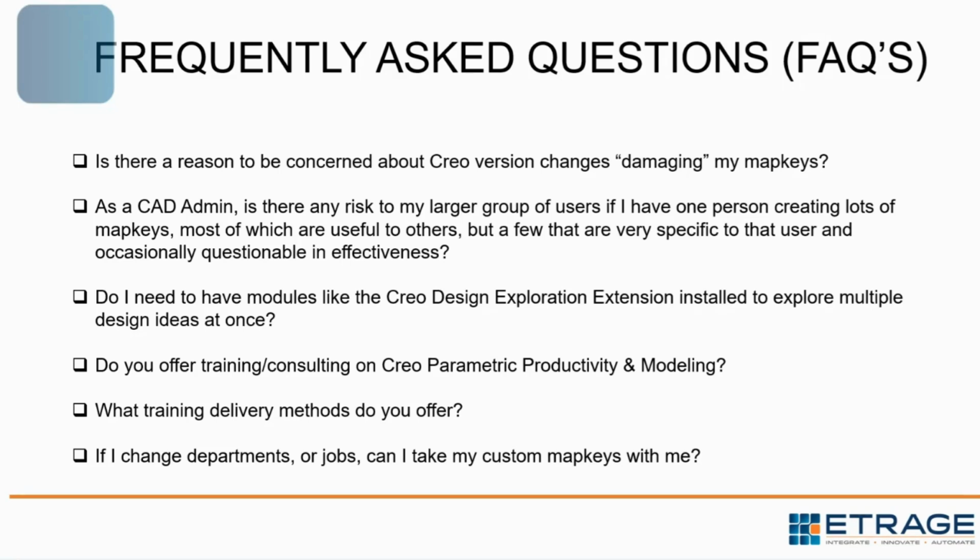It's much easier to use a design exploration extension. We don't have time to get into it now, but it's a UI session you get into where Creo stores all the different design alternatives for you. So you could resume and suppress particular sets of features, create other sets of features in one particular checkpoint. You can add new components, remove components, right? It's essentially like a sandbox where you can test out an infinite number of ideas, without them affecting your core Creo model.